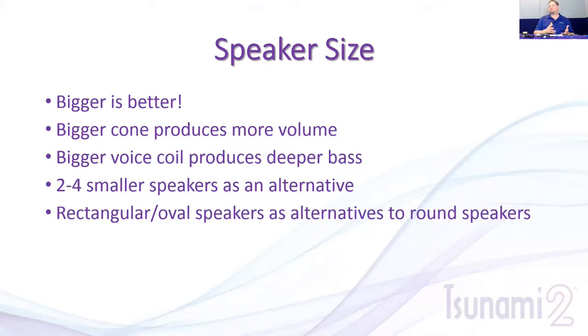So when we get into speaker size, bigger is better. And I'll say that in pretty much 90% of the cases, and we'll cover that in just a minute. Part of why is because when you have a bigger speaker, typically that speaker travel is going to be deeper and longer. And the bigger cone is also going to produce more volume. So when I take a small speaker like our small mini cube and compare it to, say, our 1.1 inch mega bass speaker, we can say this one's going to be able to produce a lot higher volume than something coming out of a very small speaker. And volume, again, is pressure, and so the bigger the cone, the more pressure it's able to reproduce.